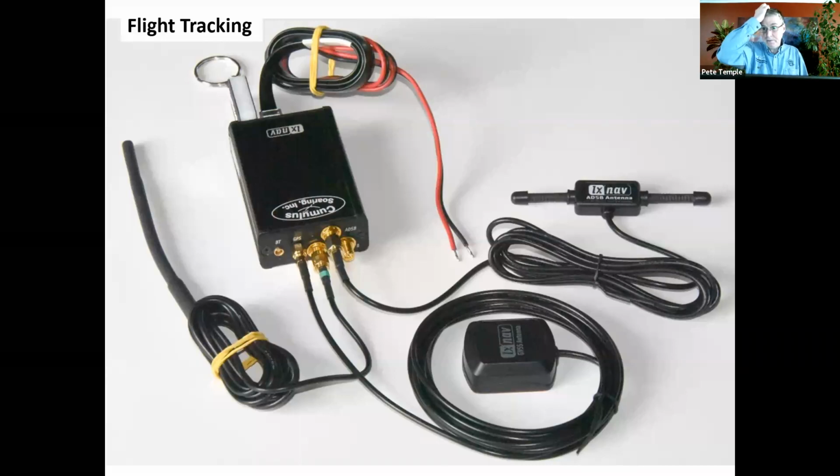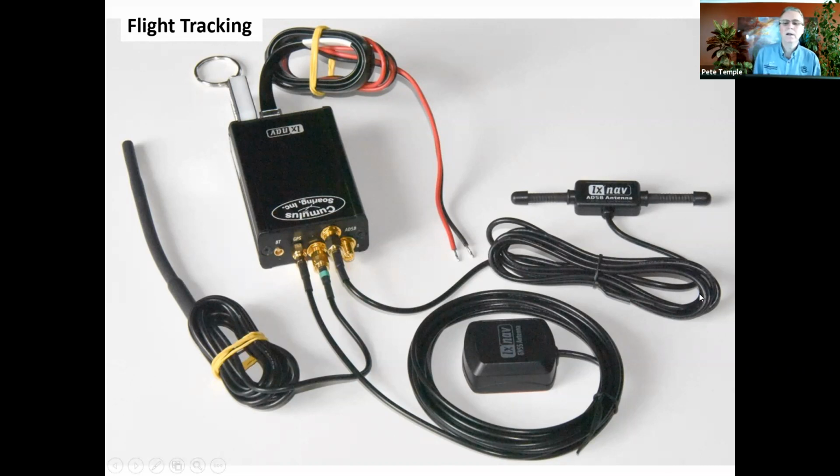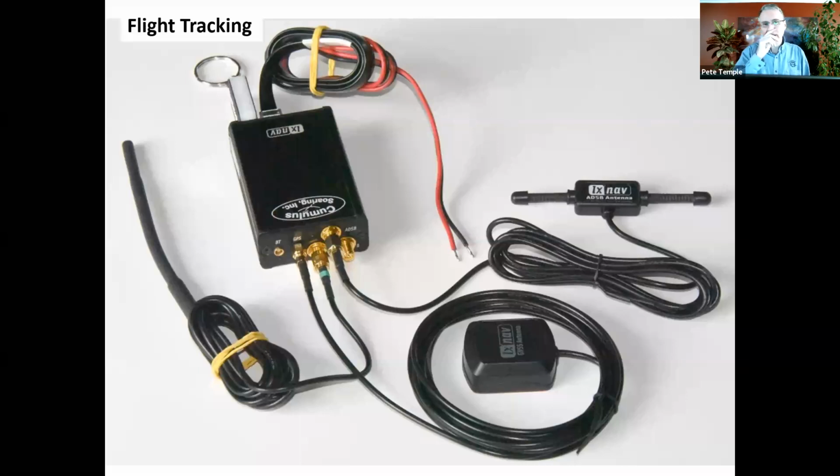That was the mid-2000s, and since then it's now integrated with ADS-B. At this stage, ADS-B in only, it doesn't transmit the ADS-B location. It has in it a database of ground obstacles. It's not very useful in Australia, but certainly when you're flying in alpine regions, they're particularly concerned about ski lifts and cables stretched across valleys and things like that, which gliders have a habit of running into. And it will warn pilots about those as well.